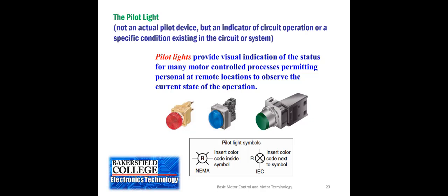Those panels usually are touch sensitive, so you'll press on one of the pictures or symbols or icons, and then a different menu will come up and show you more specifics. Those HMI panels are starting to replace the push button switches, the pilot lights, and the selector switches that you're seeing. Those HMI panels are connected to the controller or the PLC that is operating that piece of equipment.